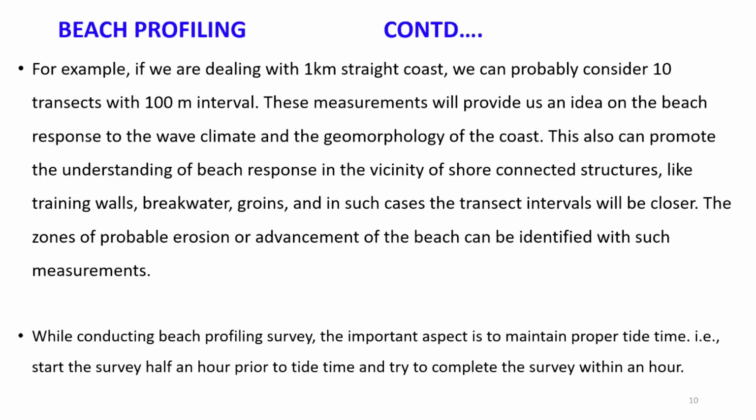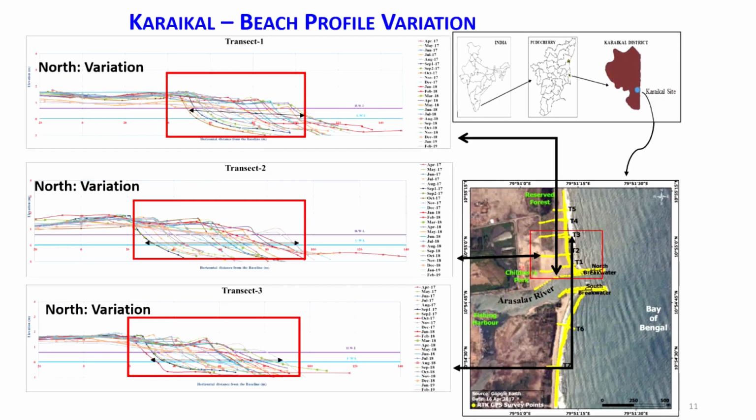One important aspect is to maintain proper tide time. That is, start the survey half an hour prior to the tide time, that is spring tide, and try to complete the survey within an hour or hour and a half. So this is how the beach profile is done.